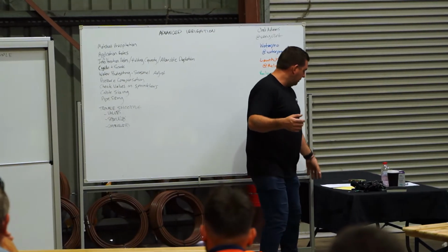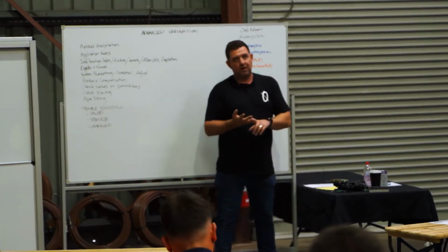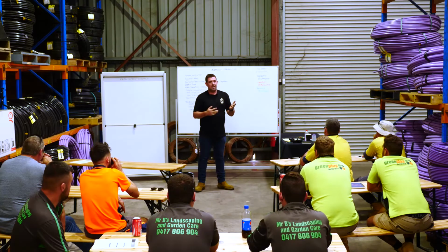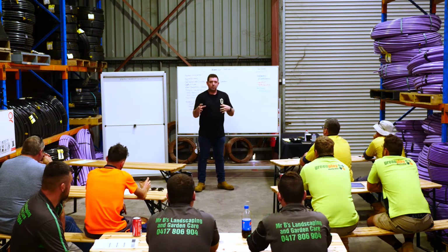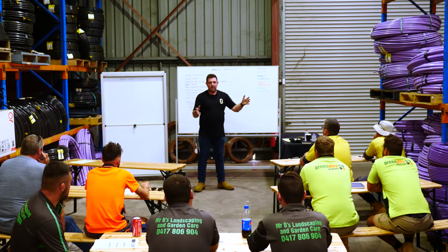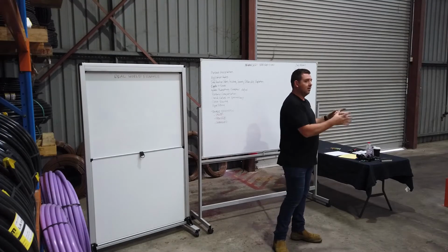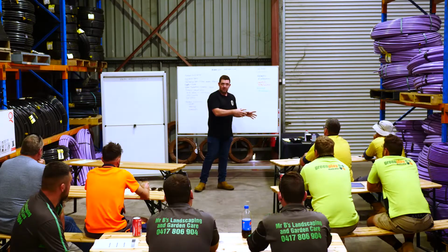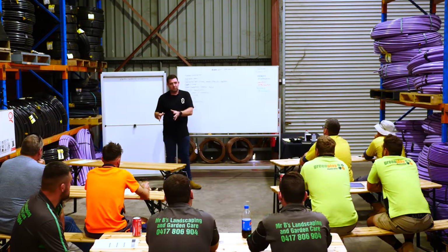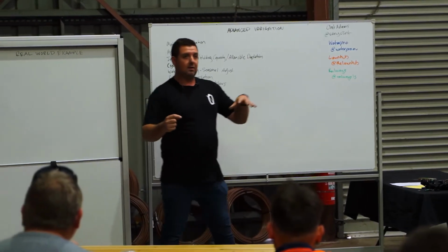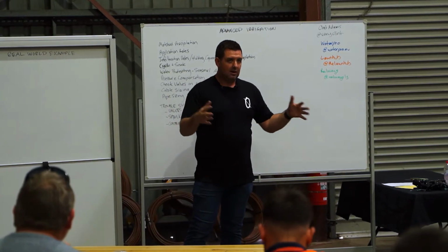Now, the products like the MP rotator, the Rainbird R-Van, and I think the Rainbird 5000 have a matched precipitation nozzle. They can realistically be designed in any configuration, and they'll generally match. Obviously the 800 SR and the 3500s for the MPs won't necessarily match with the 1s, 2s and 3s. And then obviously you move to the R-Vans, which match with each other, and then you can use the 5000 matched precipitation nozzles in a situation with R-Vans, and you're going to get matched precipitation.